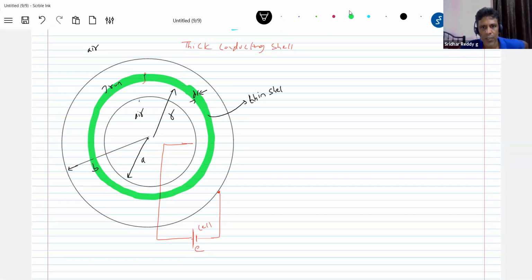Now, very first question: sir, why did you assume a shell? How will the current actually flow here? What is the direction of current? It will be radially outward, no? Everywhere the current density will be directed like this. So we should assume an elemental structure in such a way that the current density is directed normal to the surface area. I'm giving the direction of J.